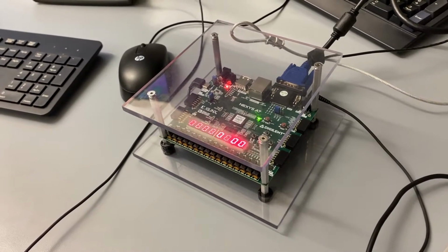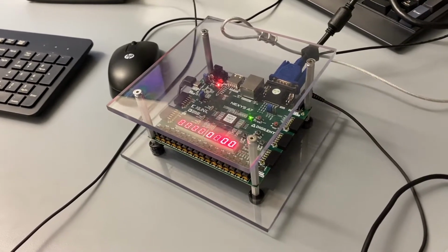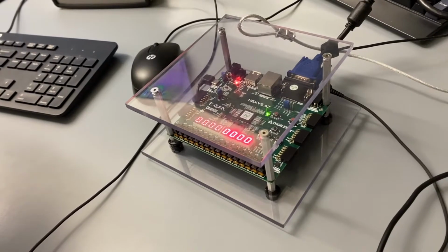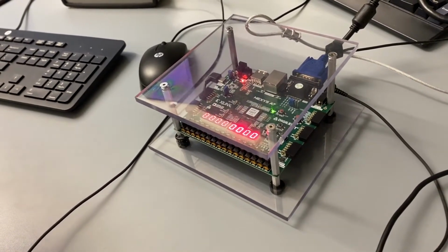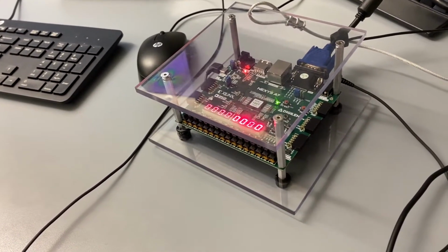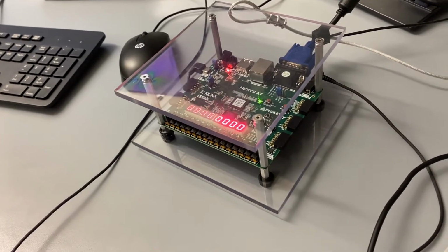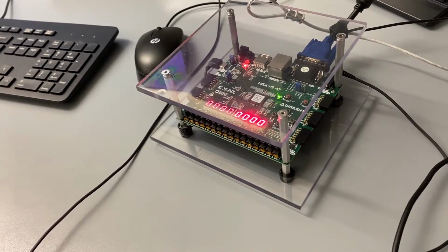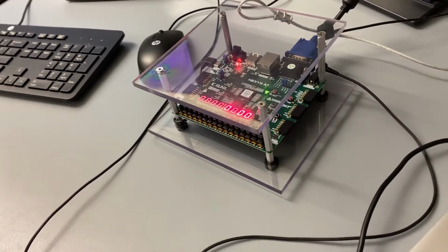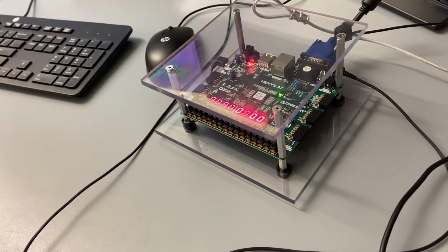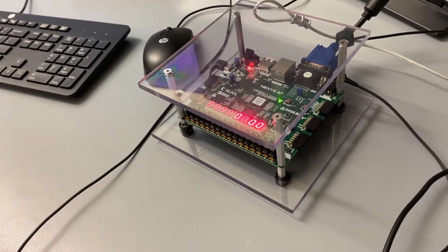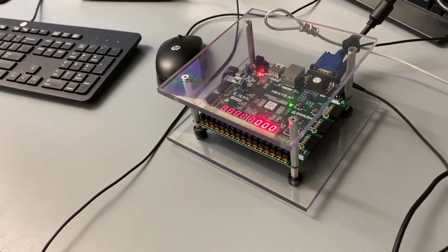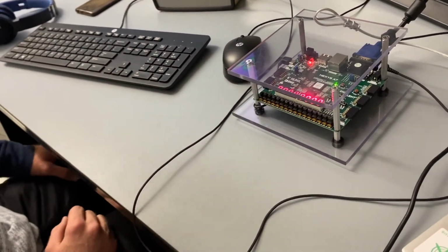So this is a demo of our Lab 3 where we built onto our Lab 2 calc and made a calculator game where the user inputs their answer using a push button, and based on their answer, it compares it to the actual correct answer calculated by the ALU. If it's correct, a green screen appears with a song being played, and if there's a wrong answer, a red smiley face will appear on the screen and there will be no sound. So now we are going to demo it.